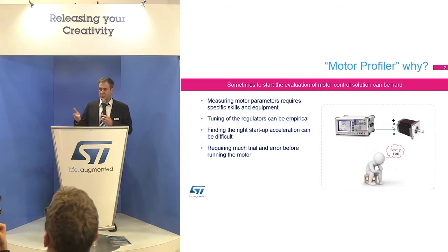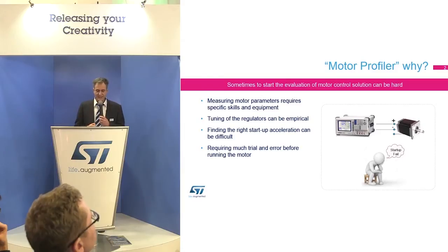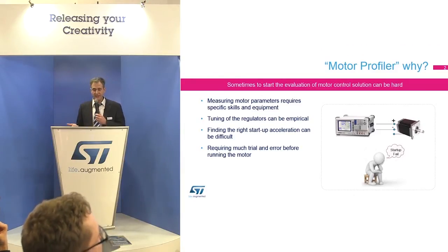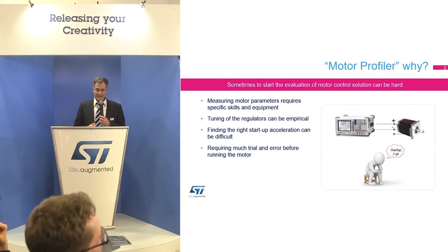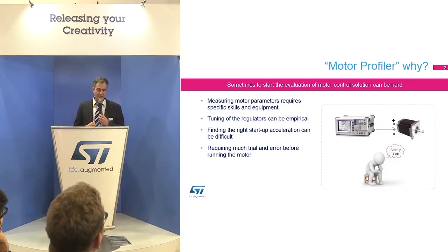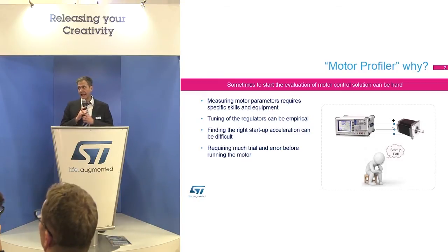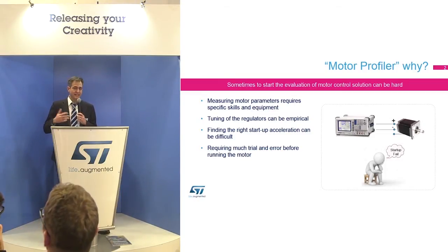Sometimes the tuning of the regulators inside the algorithm can be empirical, and you need to find the proper acceleration for the startup phase according to the load, and this can be difficult. And we can have a lot of trial and error before starting the control of the motor.